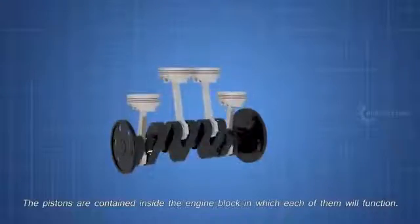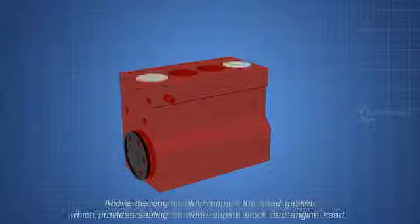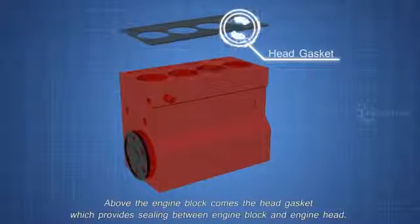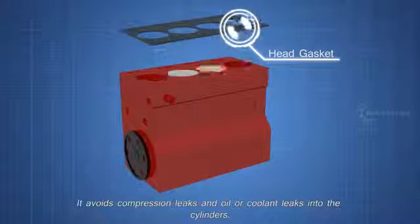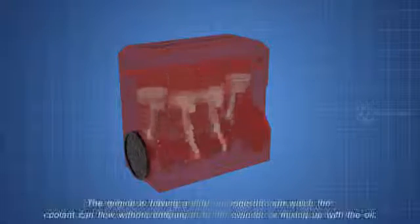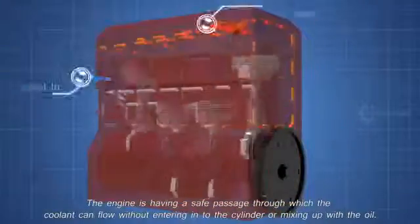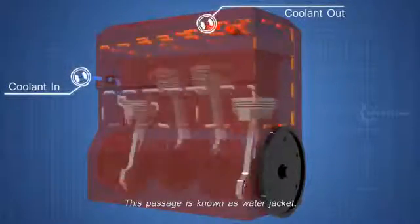Now, let's see how these parts work together. The pistons are contained inside the engine block, in which each of them will function. Above the engine block comes the head gasket, which provides sealing between the engine block and engine head. It avoids compression leaks and oil or coolant leaks into the cylinders. Above that comes the engine head. The engine head has a safe passage through which the coolant can flow without entering into the cylinder or mixing up with the oil. This passage is known as the water jacket.